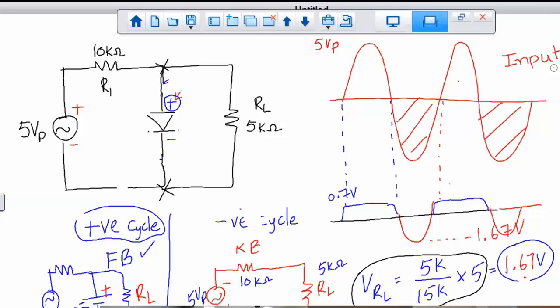Whenever the diode is reverse bias, you can always take away that branch that the diode has. That's always going to give you a voltage divider. But what cycle makes it reverse bias would be different. I'm clearly saying it's only the diode perspective, not what cycle makes it reverse bias. Do not think that the negative cycle always makes reverse bias. No, that's not true, all right?